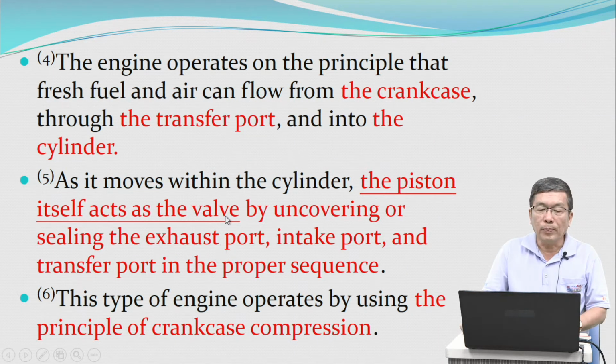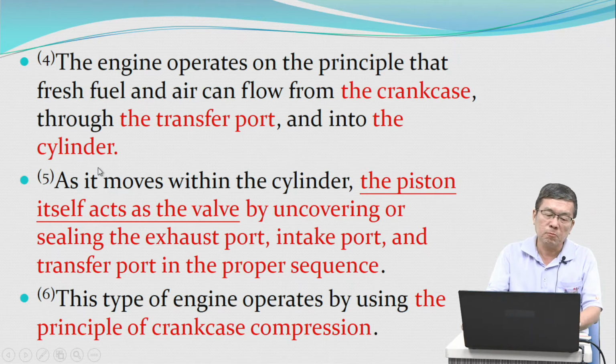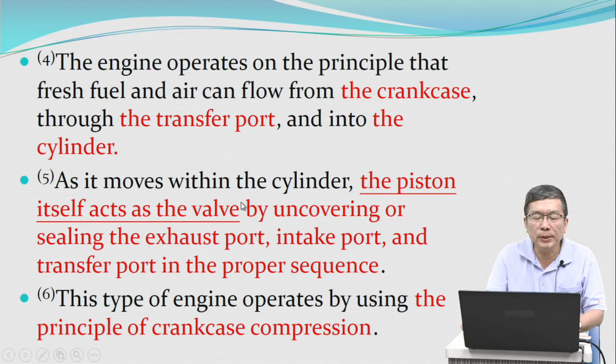The engine operates on the principle that fresh fuel and air can flow from the crankcase through the transfer port and into the cylinder. As it moves within the cylinder, the piston itself acts as the valve by covering or sealing the exhaust port, intake port, and the transfer port in the proper sequence.